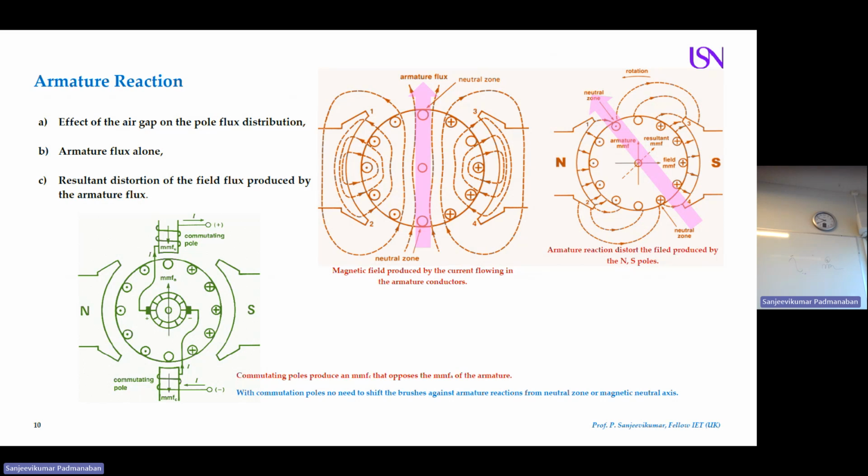At the angle of the neutral axis, sometimes you can have an interconnection between north and south pole. For example, here the coils may mismatch, in the simplest way. I'm not talking in much detail. Sometimes the coil may have the same polarity in the neutral axis and create a short circuit.